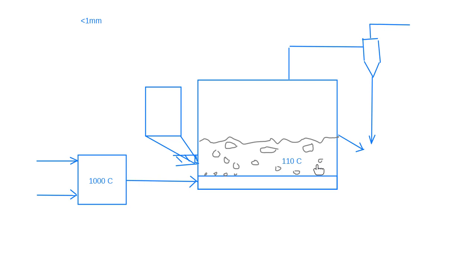So the particles have to be loose. If they're cohesive, you will not get your bed to fluidize. And if they're too big, it will also not fluidize. So when you have particles that are not cohesive and less than 1 millimeter in diameter, or less than 2 millimeters even in some cases, depending on the density of the particles, then it is probably a good idea to use a fluidized bed dryer because it is fairly efficient and easy to operate. So that's it.